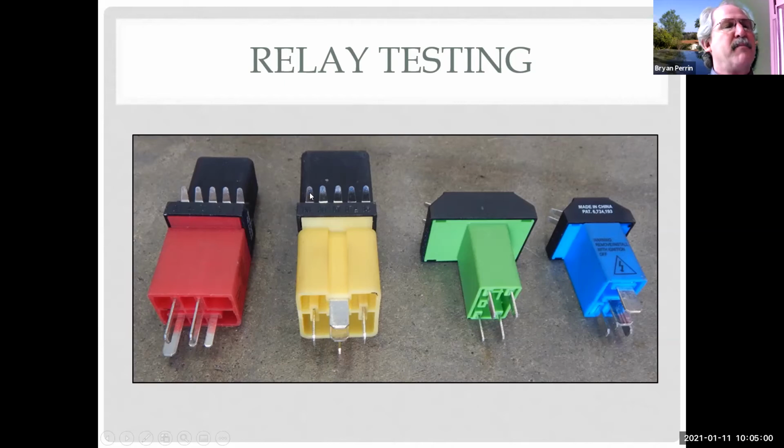So now I can hook a meter to it. I could use a power probe. I can do all kinds of things and watch and test the circuit with the relay connected because this is plugged into the relay box. The relay is plugged into the top of it. And then I can do all my testing. And you'll see me do this in the cooling system demonstration I do. I actually use one of these. But these are one of my favorite tools.